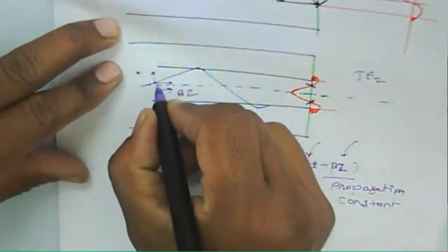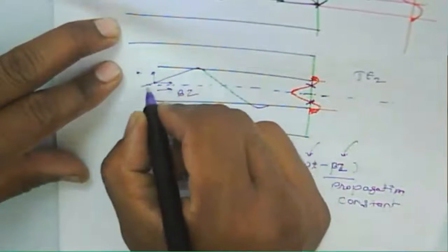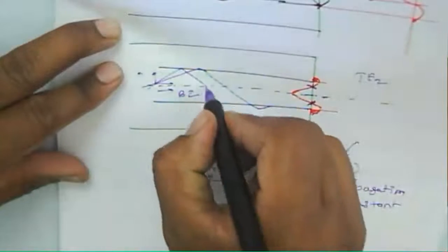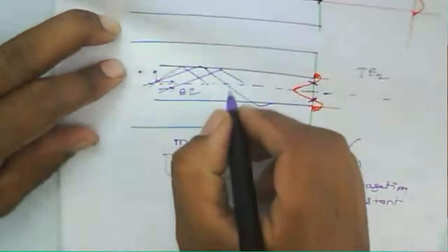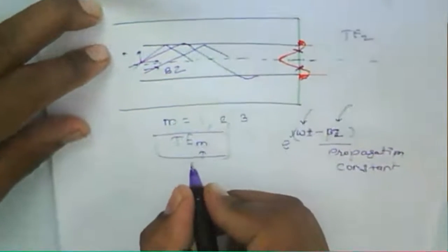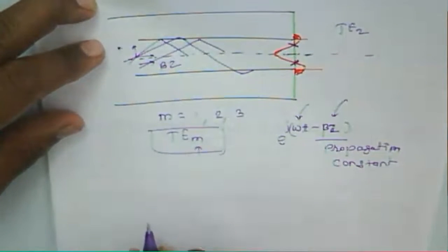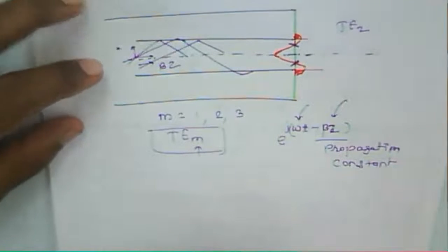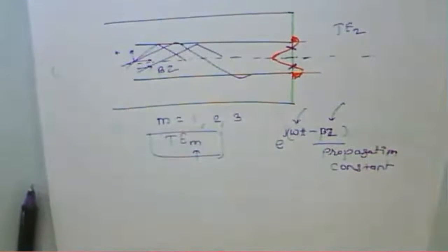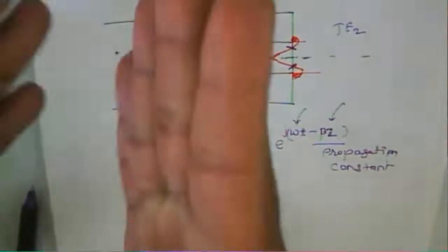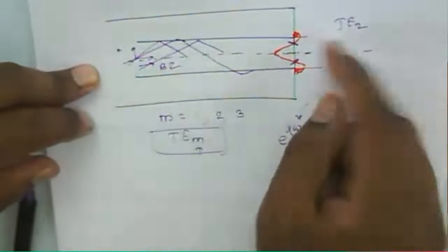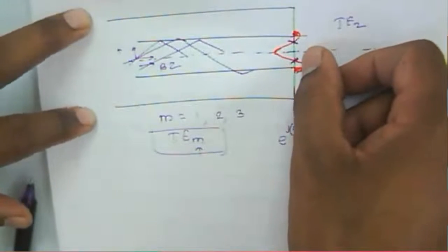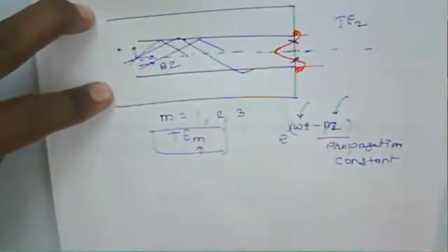Different rays means one ray is propagating at one point, while another ray is reflecting from that point, and likewise. So this way we can say they propagate through the given fiber at specific different angles. From the observer's point of view, the different rays reach the boundary at different points, so there may be a propagation delay, because of the different rays.